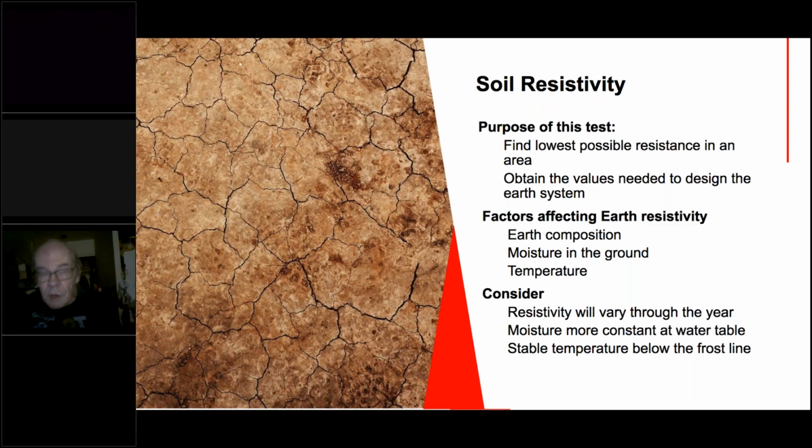Resistivity typically is the electrical conductance of the soil, its ability to conduct current. So you want low resistivity for a good ground. If you do have land at your disposal, like you wanted to put in a tower someplace and have lightning protection, the spot where the resistivity is the lowest would be the place to do your installation.